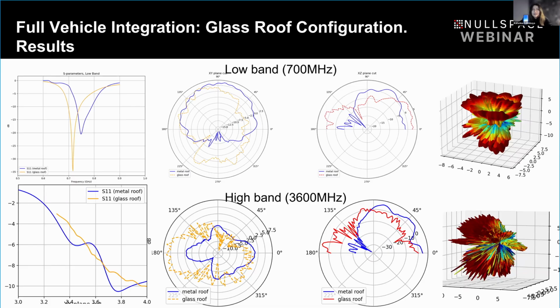So if you use the same antenna, for example, in this case, if we use this antenna on our car, because it's the same car, we just change the roof, like in Henrik's case, right? It's just a different roof material. So here it will not work already because the resonance shifted enough to have a potential problem with matching, right? So you need to think about that and maybe design an antenna that has a broader match in that area that you want to cover with different configurations, or you need to really simulate in different configurations and see what comes from that.